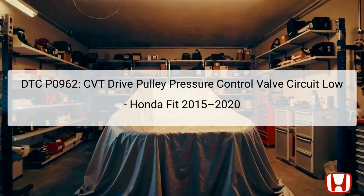The diagnostic trouble code P0962 indicates an issue with the continuously variable transmission, CVT, drive pulley pressure control valve circuit. This error primarily signifies that the electrical circuit related to the pressure control valve is functioning abnormally, typically showing low pressure. The CVT, or continuously variable transmission, is responsible for providing a smooth engine power delivery and reducing fuel consumption by adjusting gear ratios without traditional shift points.